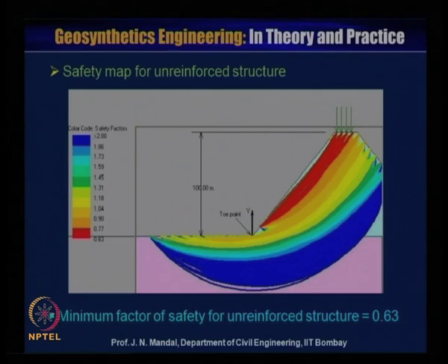Now you can see the safety map for the unreinforced structure. First of all, we have performed the analysis to find out the minimum factor of safety for the unreinforced structure. Here you can see the critical surface.